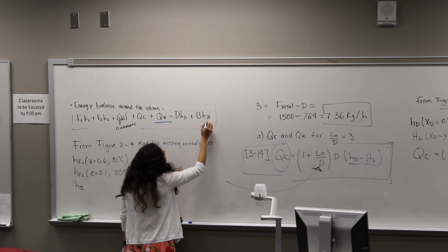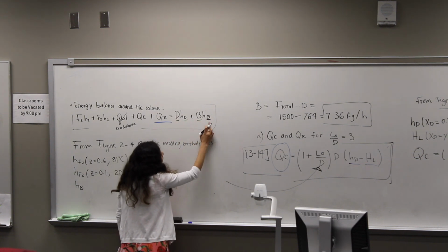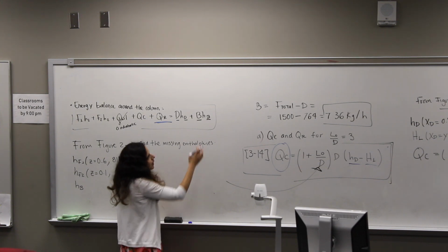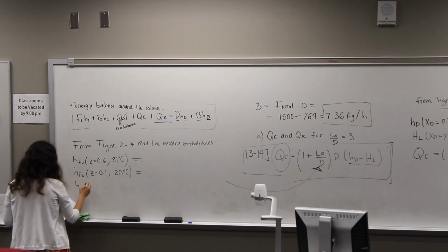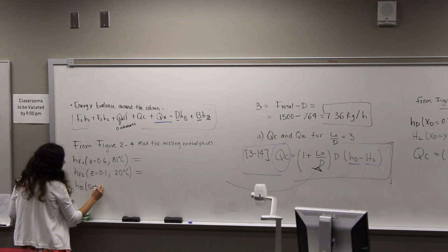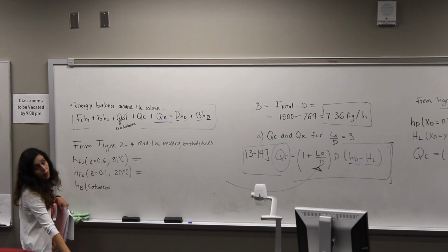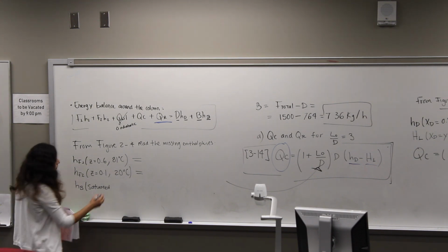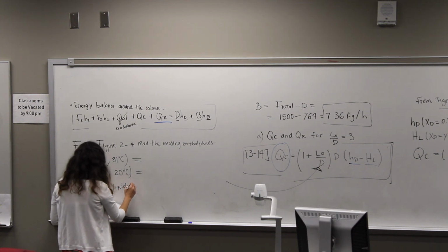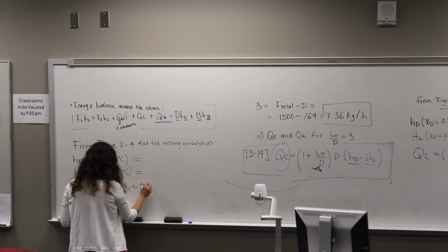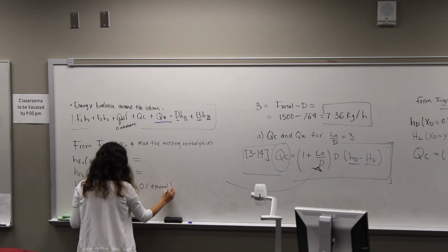All the time these go with this design, the flow and the enthalpy, so it should be the same. I put a D here, now it's B for bottom. The bottom is saturated. What do we have in the bottom, liquid or vapor? Liquid. So you need to read the saturated liquid, and approximately we will have 0% ethanol.